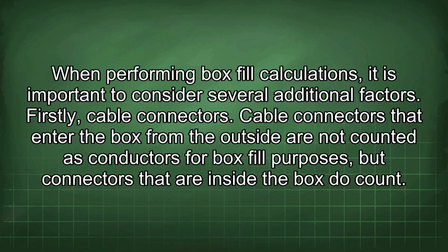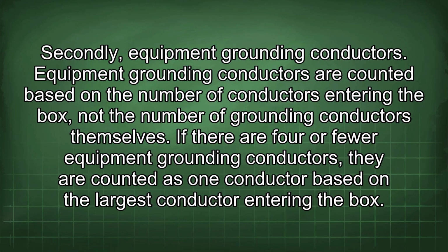When performing box fill calculations, it is important to consider several additional factors. Firstly, cable connectors. Cable connectors that enter the box from the outside are not counted as conductors for box fill purposes, but connectors that are inside the box do count. Secondly, equipment grounding conductors. Equipment grounding conductors are counted based on the number of conductors entering the box, not the number of grounding conductors themselves.